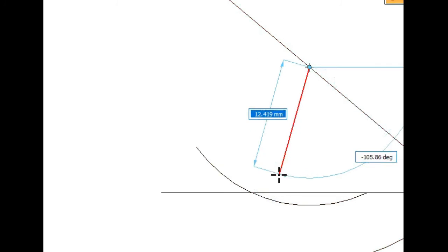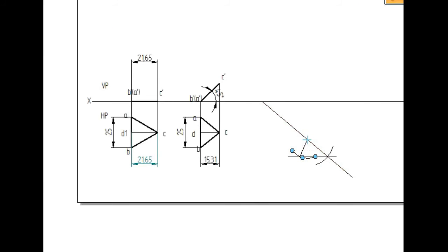So I will mark the line. Now I will extend the line. Extend this line. See, you can check here the angle. What is the angle that has been obtained here? Initially we took a line of 40 degrees, right? With respect to the 40 degree line, we took the 21.65 length and cut the arc. Now to get the beta angle, we took this 15.31 and from the same point cut an arc of 15.31, and the angle that has been measured will be the beta angle.